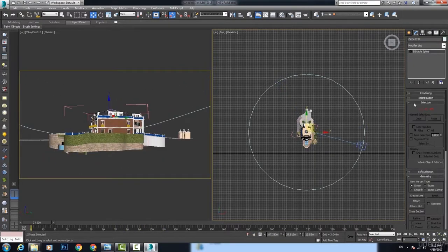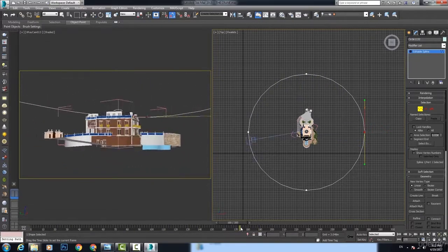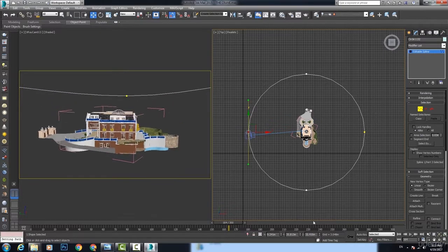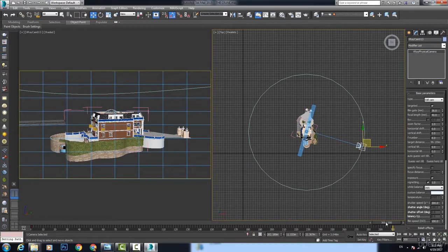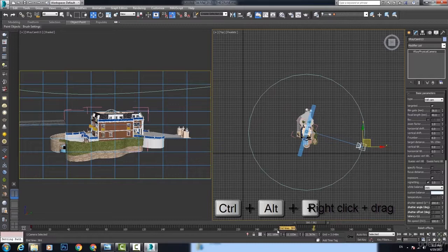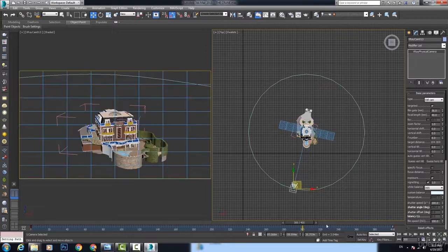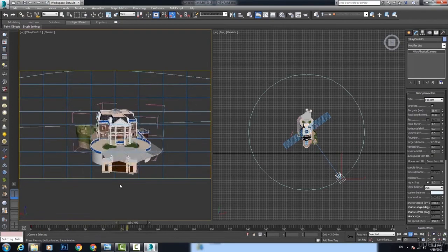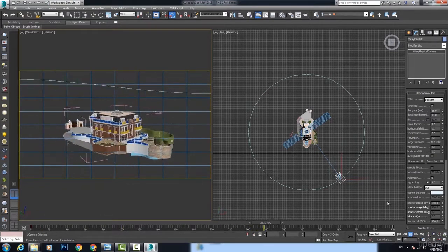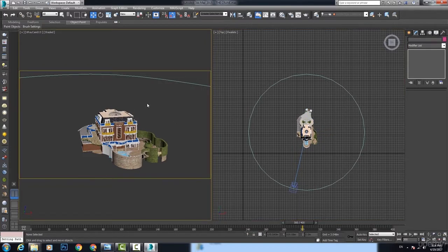I also did some refinements to the points on the circle. And increased the timeline to 400 frames so I can increase my animation frames and get a slower movement. Now my camera is refined and slower, and nothing is cropped in the movement. I made that so later on I can use the alpha channel to compose the animated villa on any background.